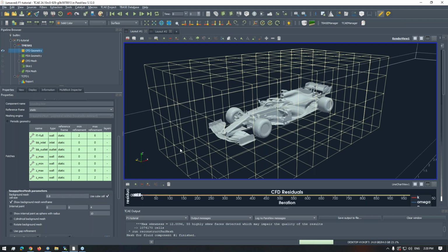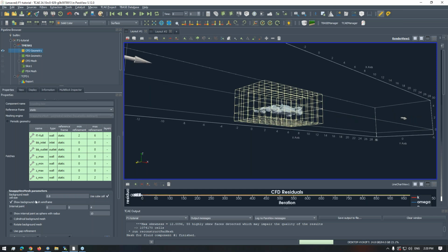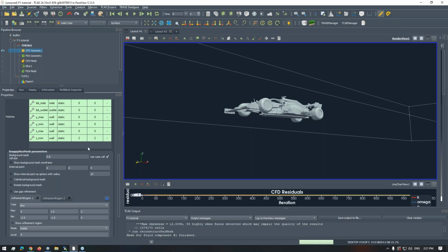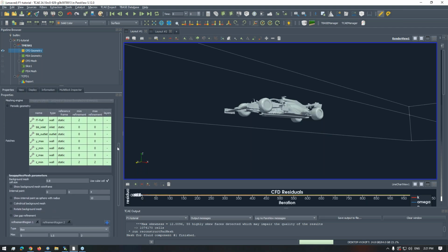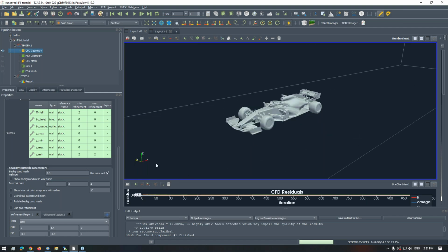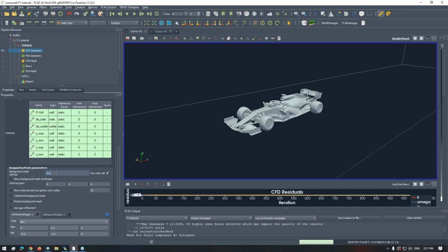You say what's your basic mesh. That's important. It's the largest cell in the volume mesh. You say its dimensions and it gets refined in the direction perpendicular to the surface, and it gets divided a couple of times, depending on your settings, and that creates your volume mesh. I know it's very condensed information, but that's what we wanted to show in this webinar. So you create the mesh with a couple of settings, but it's not that many settings. So you say the basic cube.